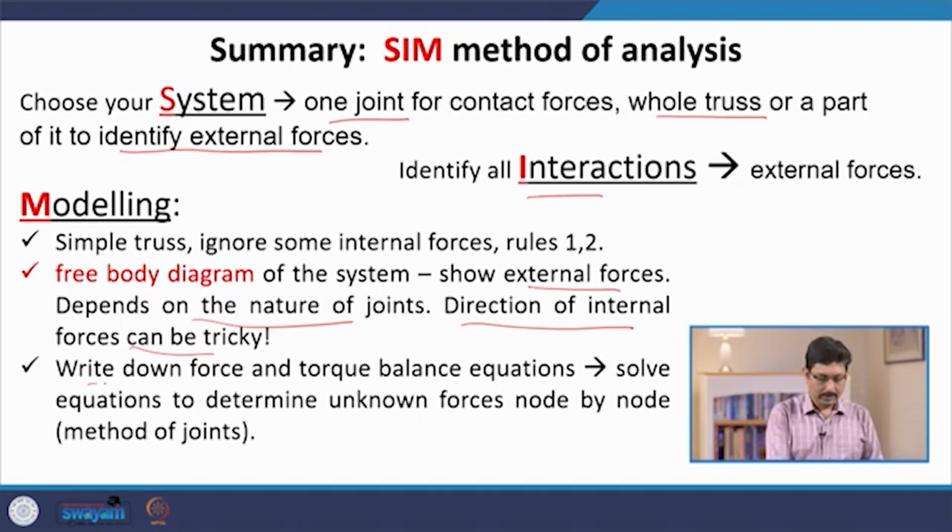Then the final step is to write down the force and torque balance equations, and solve them to get the unknown forces. Usually in the case of a truss problem, we go node by node and solve for the unknown forces node by node.